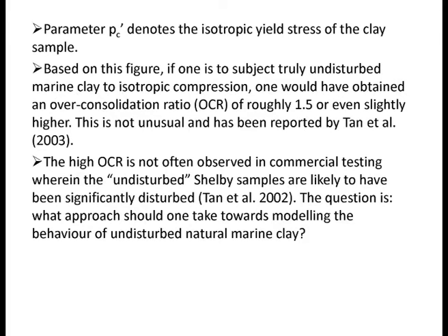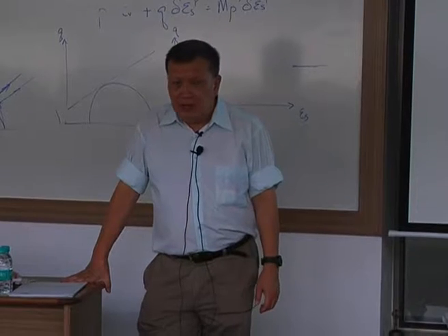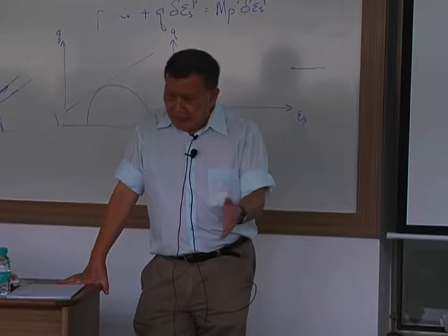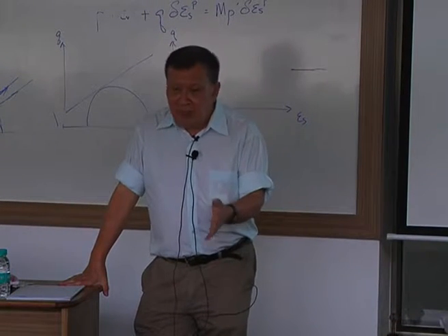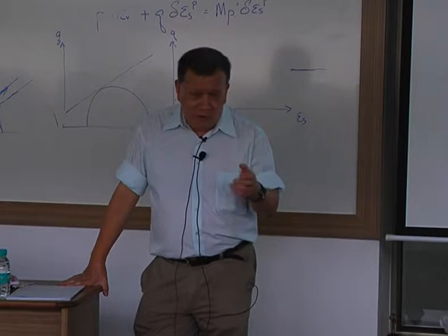So this is what it is. I think that's basically it. All right. So this kind of thing basically shows you that in natural soil condition, you may quite often encounter situations where neither the Mohr-Coulomb can work, neither the Cam-clay can work, neither the soft soil work, neither the hardening soil work. Then what works? Nothing will work perfectly.